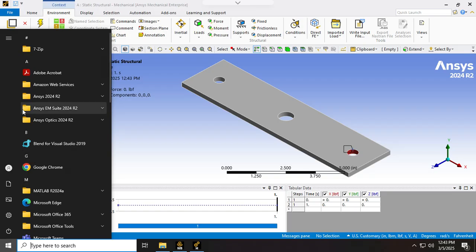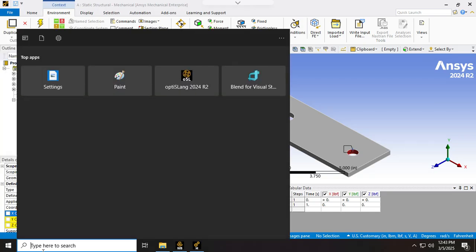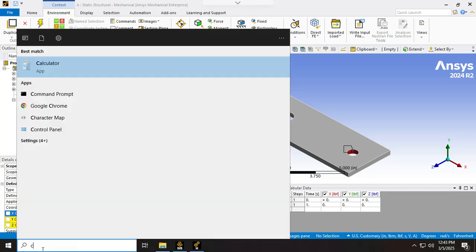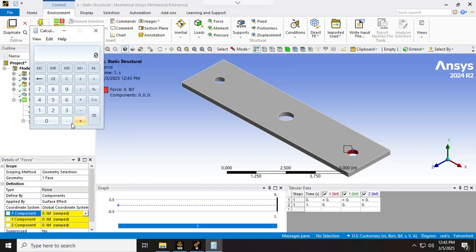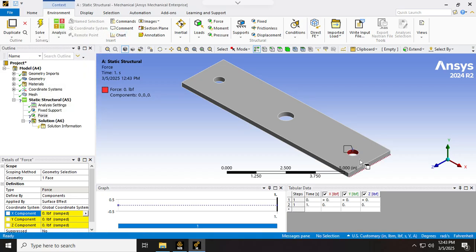In the X direction, I want to have good numbers. Stress concentration is not going to really depend on how much load you have, but my area is 2.44 thickness times 2.5 width, right? So here is the area. If I put 61 pounds of force, divided by 61, my stress is going to come out at 100. Okay, so I'm going to do that.